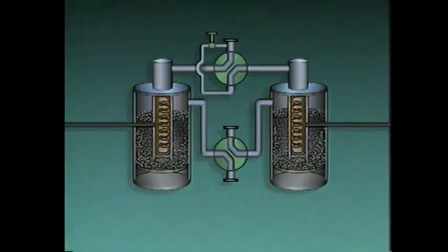The dryer also has a gas inlet, a gas outlet, a waste gas outlet, two heating coils, and two devices that are known as four-way or reversing valves. At any particular time, one of the two tanks is said to be active. An active tank contains dry desiccant that is used to remove moisture from compressed gas. In the other tank, desiccant is being dried or regenerated.